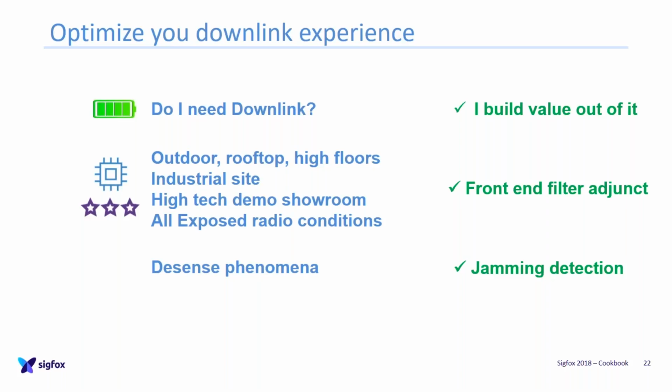For example, don't request the network to acknowledge an uplink message reception every time if your message was not extremely critical, because you would waste the energy. Managing acknowledgement is possible, of course, for very critical data or getting network link information every once in a while, but otherwise you can spare the energy budget and use it in another way.